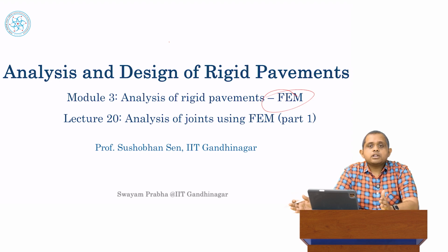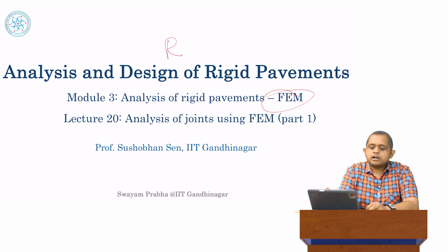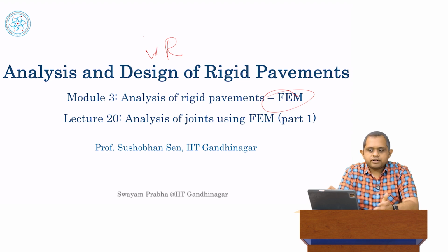On the other hand, numerical methods do not make many of those assumptions. They make other assumptions, but not the same assumptions as Westergaard's theory or analytical methods. And they start with one of the key assumptions, that there is always an error. And then they hope, as we saw, that the error may be regarded as a residual function, R(x), and it is hoped that if we multiply that by some weight function, whatever that weight function might be, and sum it up over the entire domain, so the integral of W R dx, then this is 0.